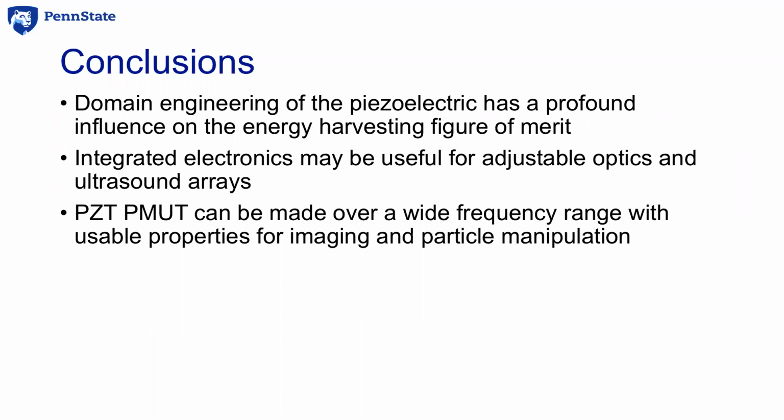As we get better and figure out where the bugs in our processing are, how long it takes to do a device run will depend on how many layers and how many patterning steps. So for the adjustable optics, just to get the piezoelectric on currently takes us a couple of weeks because of the low slumping temperature of the glass. If that were a conventional piezoelectric on silicon, it would take us a day to do that, and then maybe an additional week to do the rest of the patterning. For the micromachined ultrasound transducers, that's usually at least a month-long fab process.